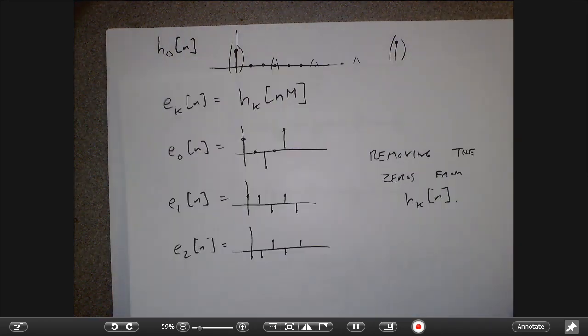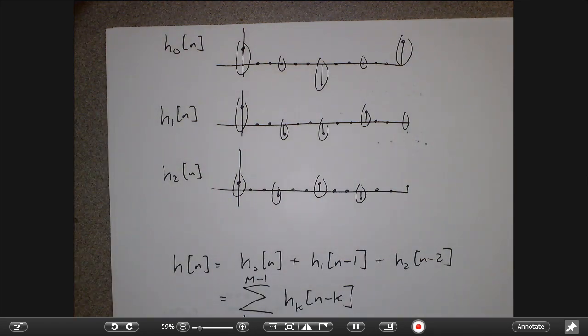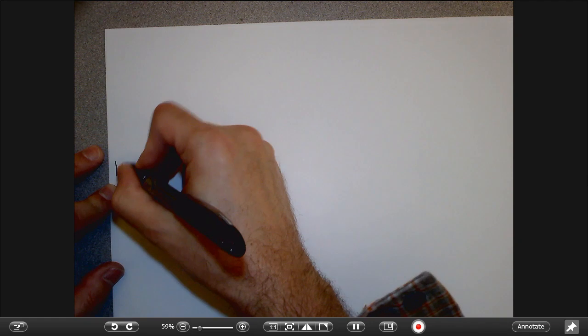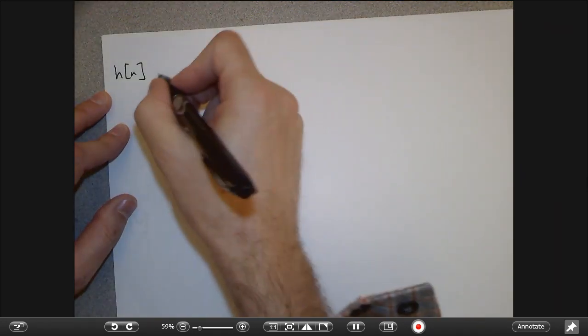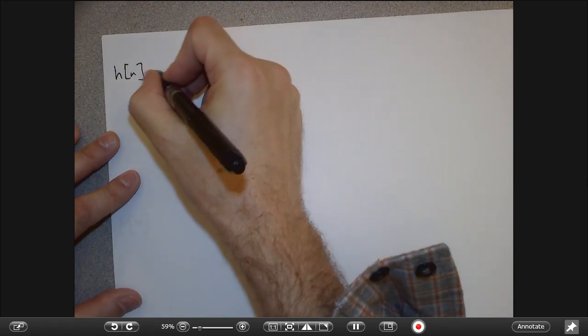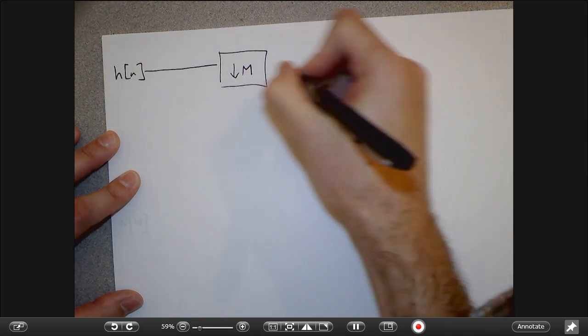So now I am going to write a complicated block diagram that is just refreshing our memory of how all this stuff works together. Okay? So what I could do is take my original signal. Actually, let me put my original signal at the top of the page. To get my first polyphase decomposition, I am going to downsample that by a factor of m, right?